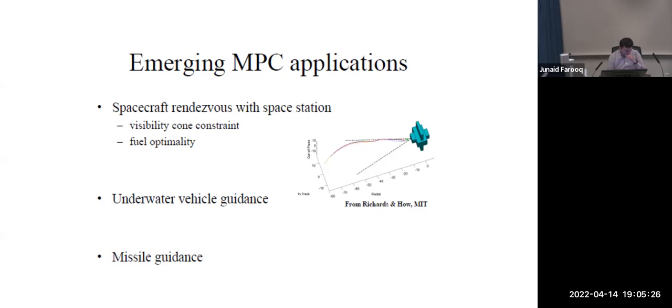What happens is there's a trajectory that it follows, and at every step of the trajectory, you optimize and readjust your control input. By doing it iteratively at every time step, you are eventually able to guide it to the exact point that you want. Otherwise, you need a model to compute the controller input and then let it go, and it might not even reach the target.